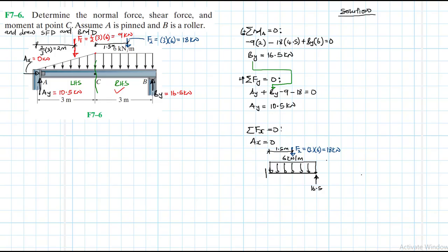Alright, so here we have a shear according to convention in that direction, like that. This point is C. We have the moment like this, MC, and then we have the normal force like that, NC. And the short distance from here to there is equal to 3 meters. So we have all the information that we need. We can apply the equations of equilibrium.